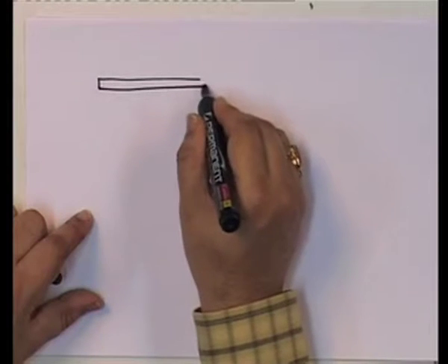The reason why I could factorize it was because when I developed it, this is actually what is known as a symmetric system. It is a symmetric system, so that the lateral displacement and the rotational displacement are uncoupled from each other, and therefore, I could factorize it. Let me take another problem in which I can't do that. And so, therefore, I go back to that original problem that we had solved.